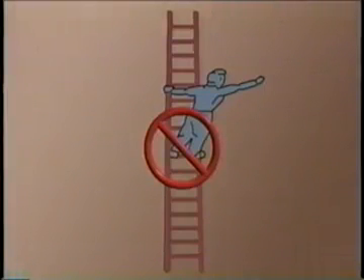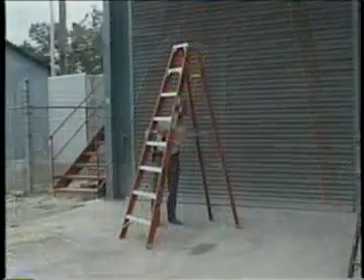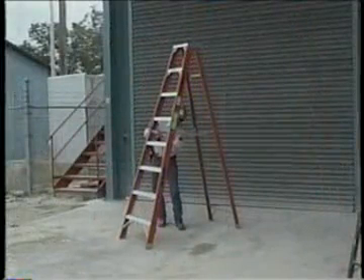Keep your weight between the center rails of the ladder. If you need to reach outside the rails, move the ladder. If you can't move the ladder, you will need to hook up a personal fall arrest system to a secure anchor point. Improper setup or improper use of the self-supporting ladder are most commonly associated with injuries. It is each employee's responsibility to thoroughly inspect the self-supporting ladder prior to use.